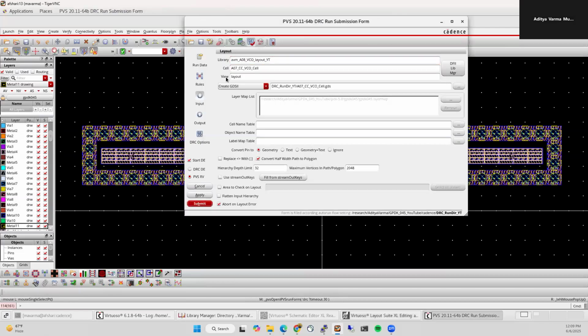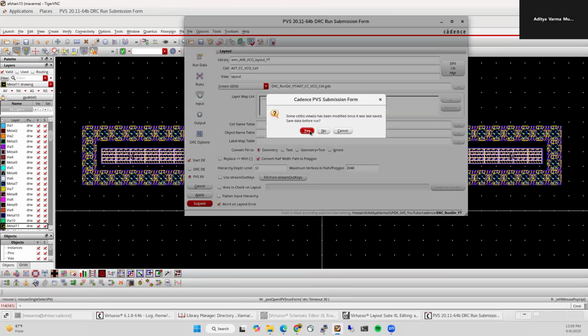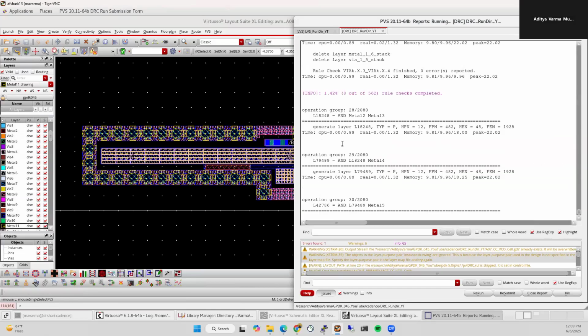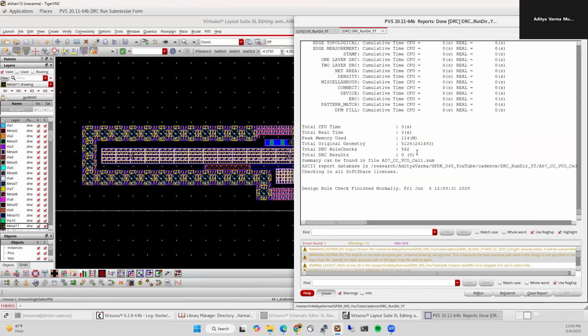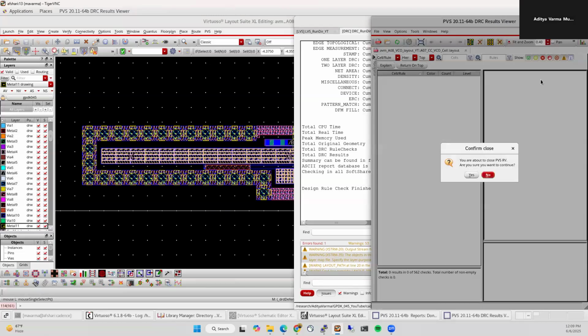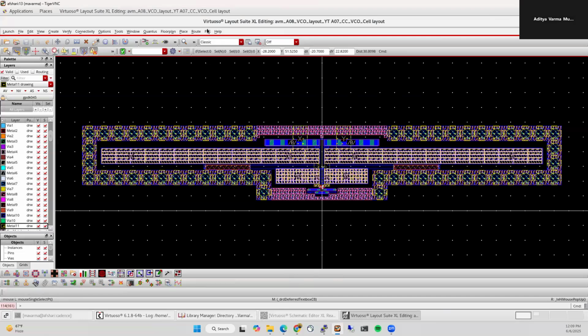I've already done a video on DRC, LVS, and PEX and how to set this up correctly. You can watch that video. But once you set it up, you can essentially just submit. And since I've already done this before, I cleared the DRC errors, as far as I remember at least. Hopefully there are no new ones. Yeah, so we have a clean DRC. And you can watch the video on DRC if you don't know how to do that. But clean DRC, and then we'll run LVS.